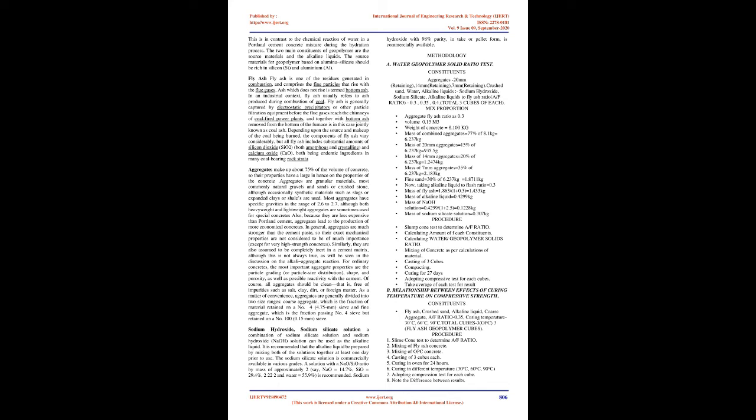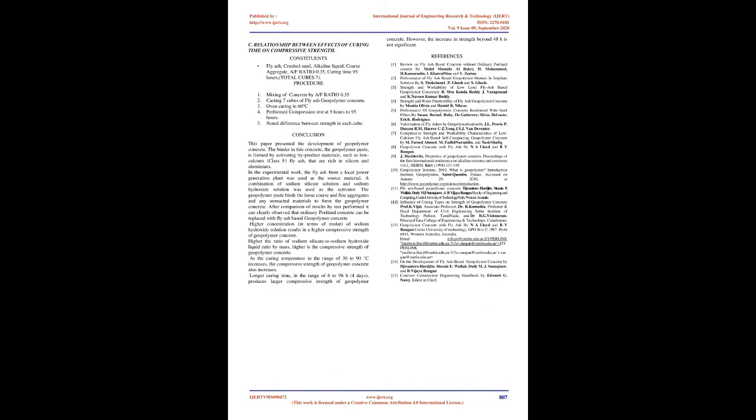In general, aggregates are much stronger than the cement paste, so their exact mechanical properties are not considered to be of much importance, except for very high-strength concretes. Similarly, they are also assumed to be completely inert in a cement matrix, although this is not always true, as will be seen in the discussion on the alkali aggregate reaction. For ordinary concretes, the most important aggregate properties are the particle grading, or particle size distribution, shape, and porosity, as well as possible reactivity with the cement.